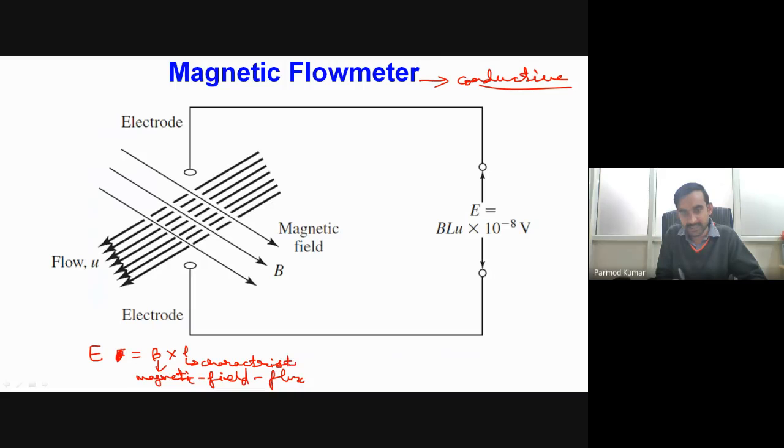In this particular case, we have a pipe through which fluid is flowing, so we can take the diameter of that pipe as our characteristic length scale, multiplied by u, where u represents the mean flow velocity at any particular cross section.